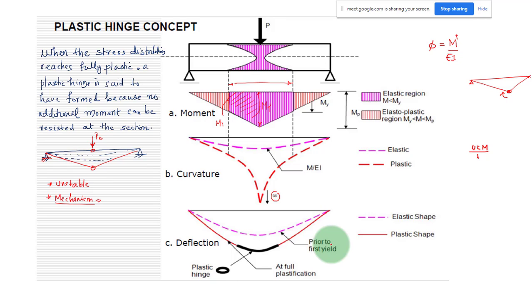The deflection should not exceed some value. For vibration there is some limit. So that is why we are following the limit state method. But this is nothing but your ultimate load method design. So I can take the ultimate strength, plastic moment, in the design, but I will keep some factor for the load. Whereas in your working stress method, I will keep some factor for the material strength.